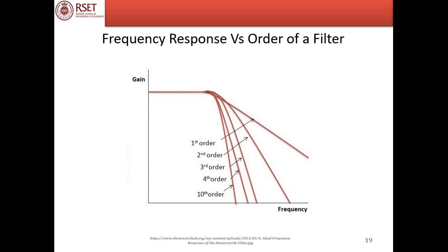In this session, we introduced filters, we defined what a filter is, we discussed the different criteria based on which filters are classified, the different classes of filters, we studied what frequency response means, we studied the frequency response of low pass, high pass, band pass and band stop filters, we introduced Butterworth filters, we introduced and understood the term order of a filter, and we saw how the frequency response of a filter approaches the frequency response of an ideal filter as the order increases.